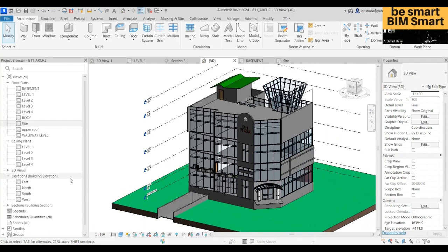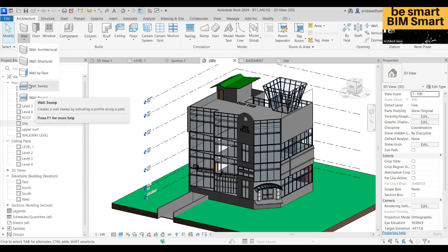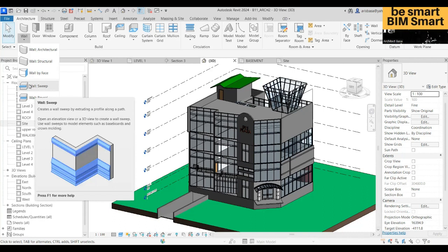Curved ceiling. Yeah, we'll do ceiling. We'll do special ceiling next week. Of course, we know how to create basic ceiling, right? But how about when you want a ceiling with different levels with some mullions like this, right? This is okay. Great mullions, we'll just use the, what's the wall? The tool? Wall sweep, right? We can just use wall sweep. But how to create special sections of wall sweep? That's what Razak is asking.